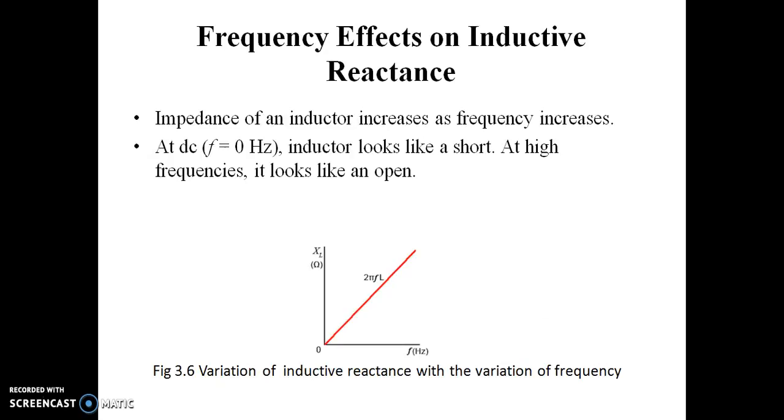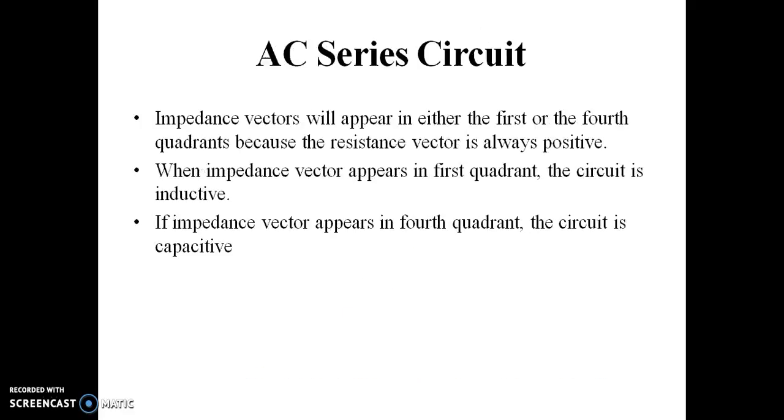Frequency effects on inductive reactance. Impedance of an inductor increases as frequency increases. At DC, that is f equal to 0 Hz, inductors look like a short. At high frequency, it looks like an open. Figure 3.6 gives variation of inductive reactance with the variation of frequency.